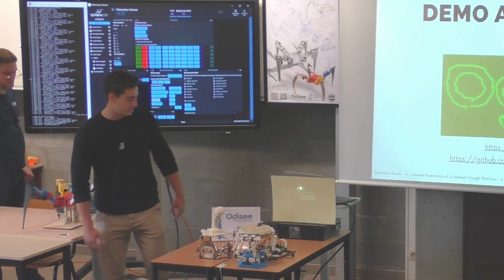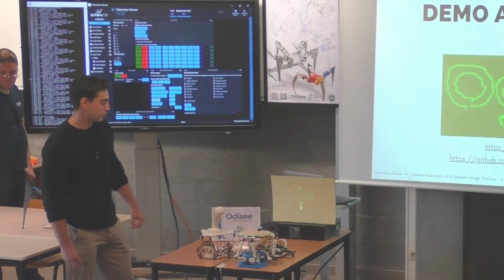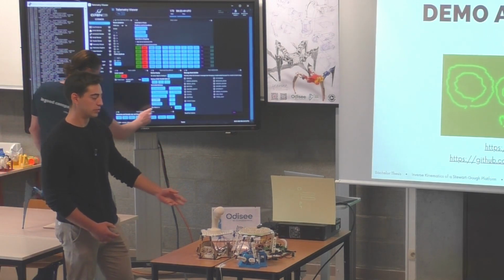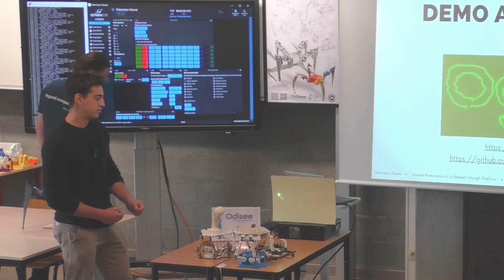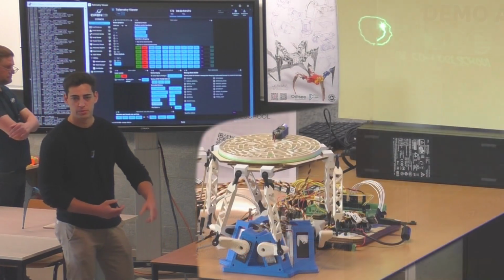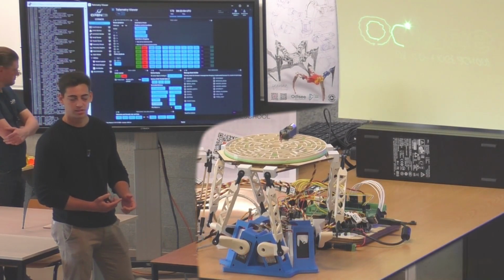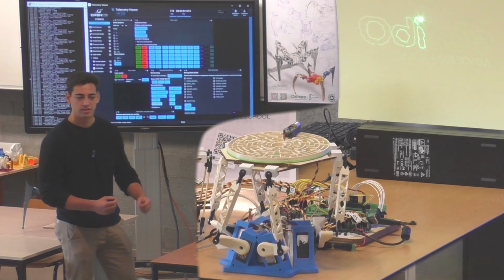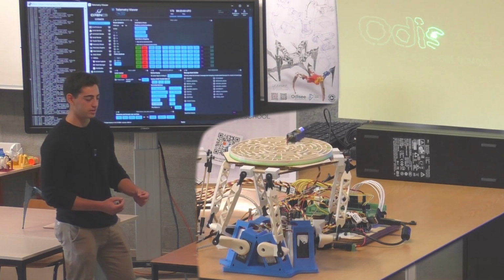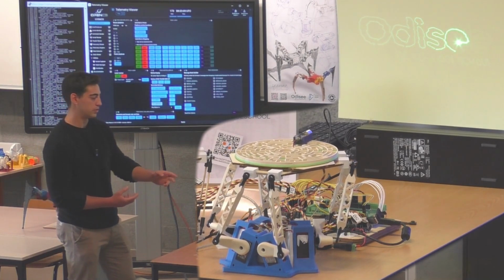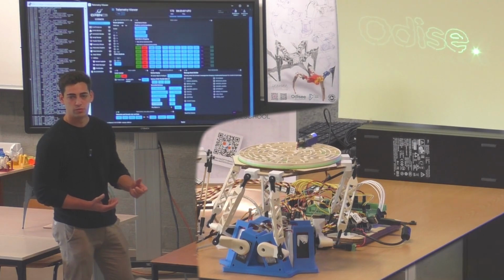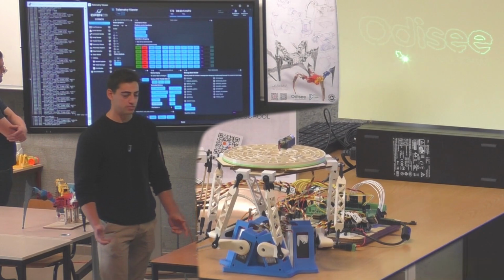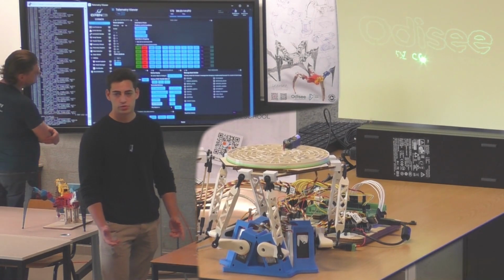Yeah, since the servo motors, we have a sequence of steps in the text file that we compile in the C++, and we have the positions of the steps, but in between those steps, we really don't know what's happening inside the servo motors. So we know that from one step to the other step, it's going to be the position that we want, but since this is not linear, then between the steps, we have no way of knowing where the platform will go. So that's why it's a bit jittery. And that's because in between the steps, we really don't control the servo motors.